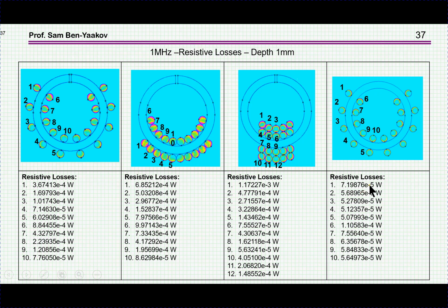And we see here 10 to the minus 5. This is probably the worst. It's minus 4. And this is also not that good. This is sort of in between. We have here lower numbers than here, of course, and here, and we can just from the color get the same impression here. So the conclusion here is that, in fact, in terms of proximity effect, the distributed gap is the best.